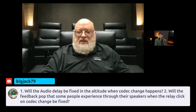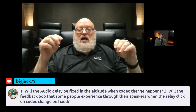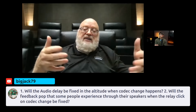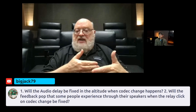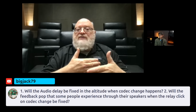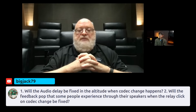On your second question, the relay click is a little bit different than a pop, and it's not actually feedback. For those of you who don't own an Altitude currently, we have relays on all of the analog outputs, and the idea is that we disconnect the analog output from what's going on inside the box until the signal settles down, because sometimes we get a dirty signal and we need to wait for it to stabilize before we want to start reproducing it, to avoid nasty kind of noises, stuff like that.